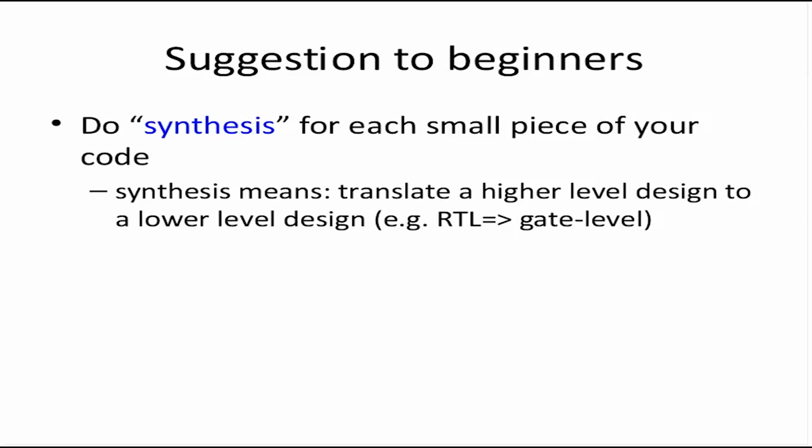Let's say you are going to design a big block which will in turn contain small blocks. It is very important that we synthesize the small blocks first, especially if we are beginning to learn synthesis, because this will make sure that we catch all the errors in the beginning itself. So let's see a few examples.